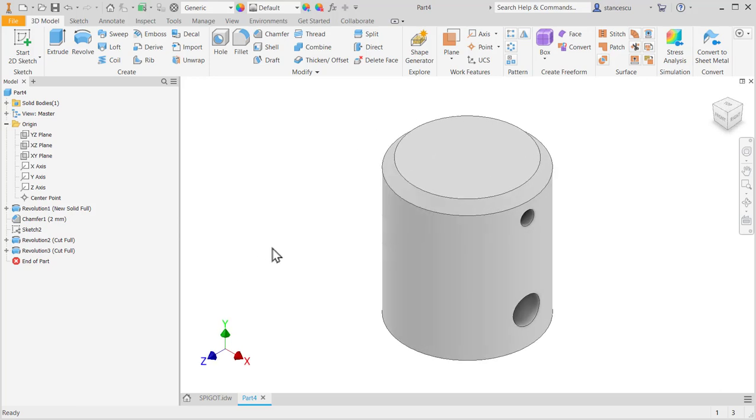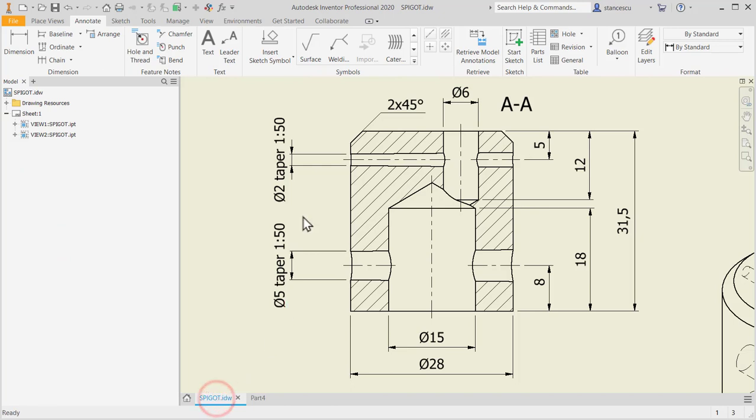And now the holes. There are two. Cylindrical, not through, with diameter. This is concentric with the part. Let's start with it. 15 with the depth of 18. 15, 18.